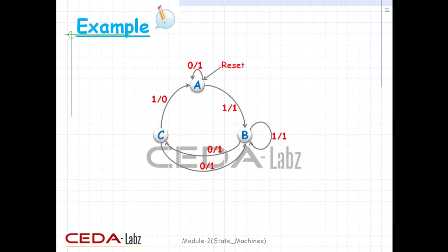States are not ports in a state machine, they are internal circuitry. A state machine has two inputs, one input and one clock, and one output. Although, the clock is for transitions. If reset is also present, then its initial state will be considered according to reset. We mostly prefer active low reset, and that too synchronous for state machines.